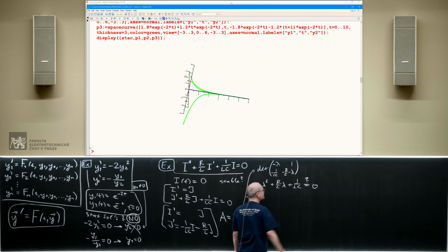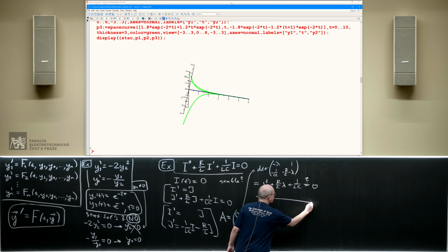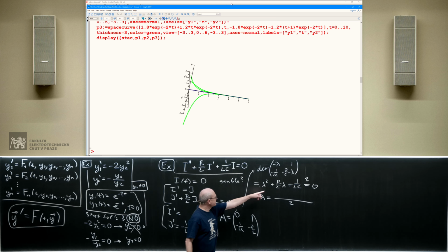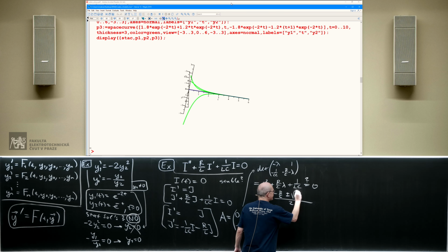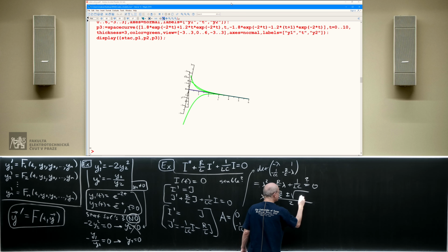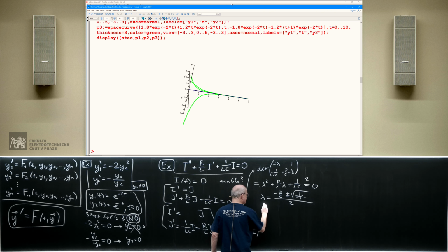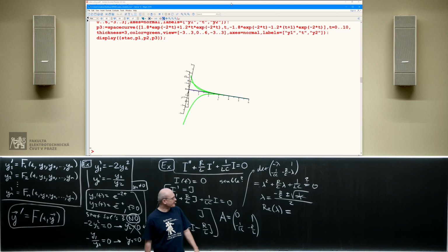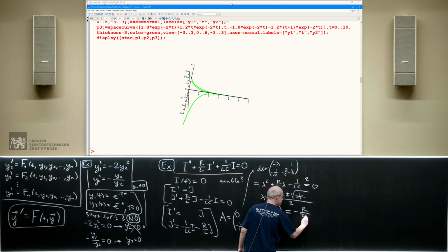And I'm asking, could this be 0? Well, let's see. We have a formula for lambda. In the denominator, twice this coefficient, which is just 1, so it's 2 over here. This guy is put here with minus, plus or minus square root of, do I care? No, I don't. There is something here. And all I care about is the real part. That's the point. When I'm asking about stability, I just look at the real part of my lambdas. What do I see? The real part is over here. It's minus R over 2L.